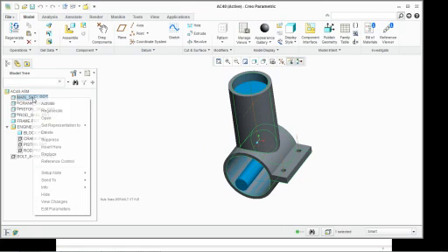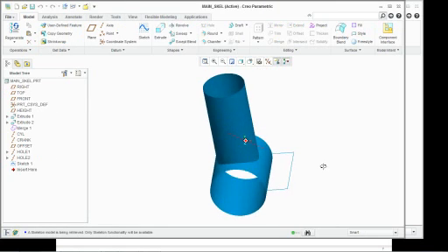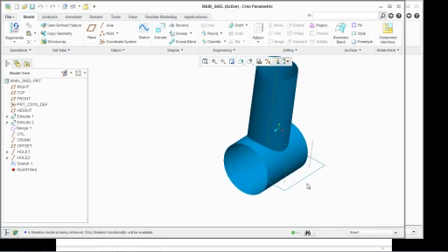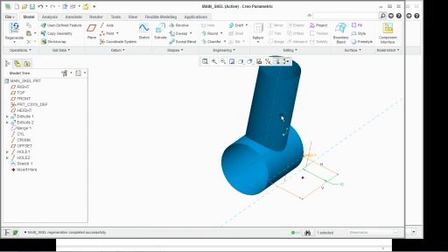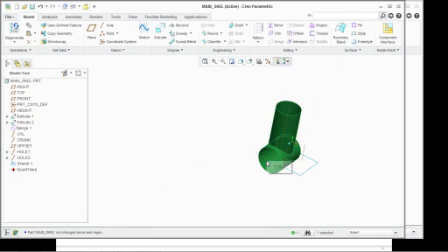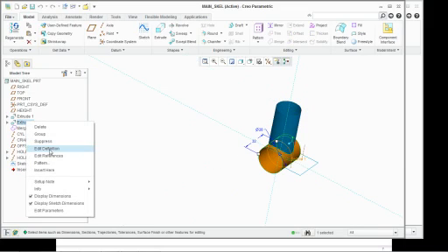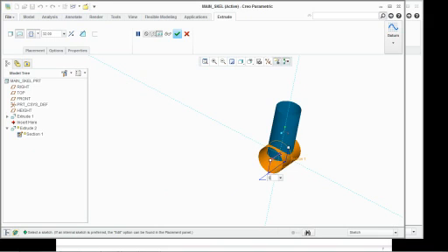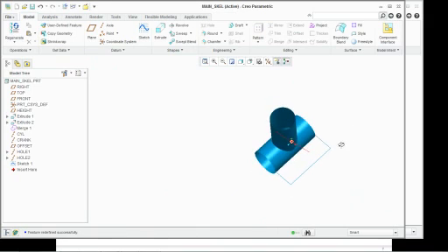But if I go into my main skeleton, which everything's based off of, we created an almost identical skeleton to this earlier. Let's say, for example, I want to edit this. So instead of 5, let's change this to 15. And maybe I want to regenerate. I want to take this top part here, and I want to edit the height of this, or maybe the diameter of this from 21 to 25. And we'll take this bottom section here and edit, extrude to, edit the definition of that to, instead of 32, maybe we'll make that 55. So we're drastically changing the design of this.